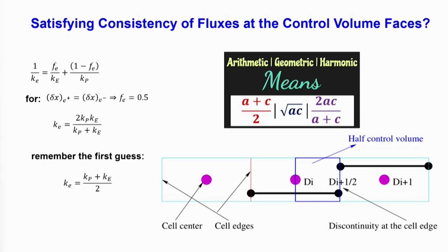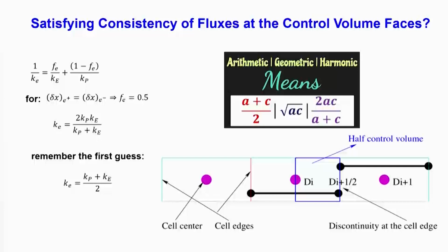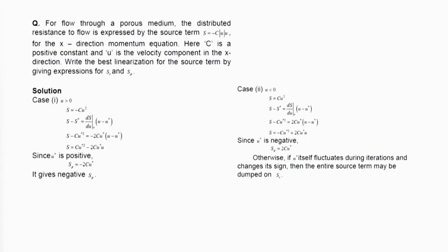So, see where mathematical intuition fails. Interpolation we always try to do linear, which for equal spacing becomes the arithmetic mean, but the physics says that it has to be the harmonic mean. So, whatever formulation we use, what is emphasized here is that we should not lose this physics and just take a blind interpolation and put it there.